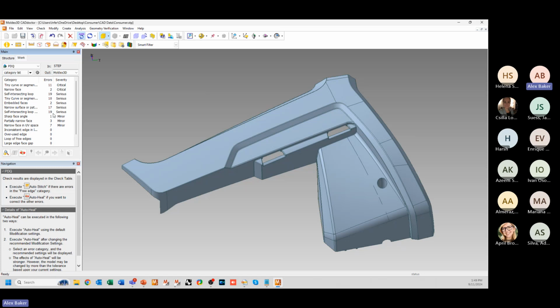We don't like to spend too much time on fixing in CAD Doctor, just because any manual effort spent in CAD Doctor isn't necessarily going to translate to a saving of time in Studio. And that's really what we use CAD Doctor for, to save any frustration and any effort required to fix the surface mesh. We want that surface mesh to be cleaned automatically, and so fixing a lot of these errors really helps us to do that. But if we have to spend a lot of time in order to prevent those errors, then it's not really worth it for us.